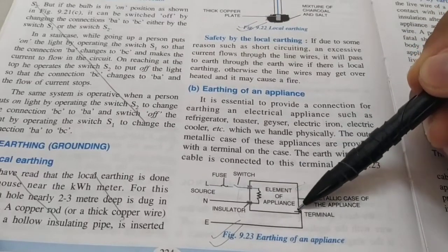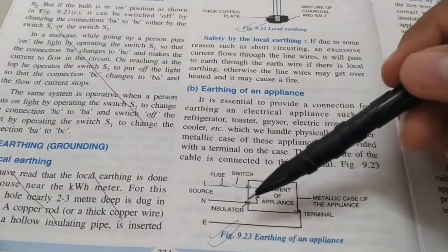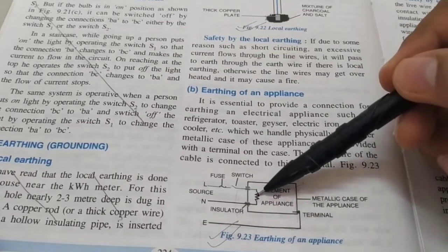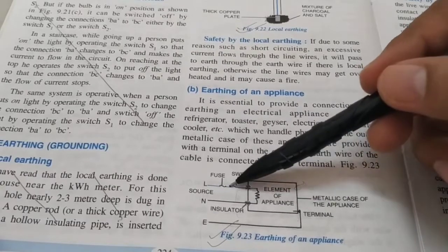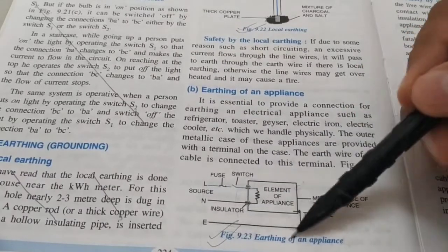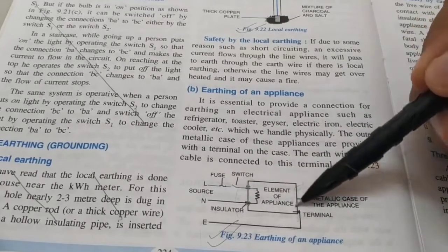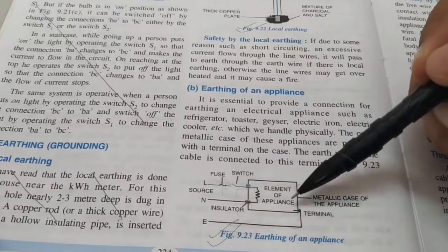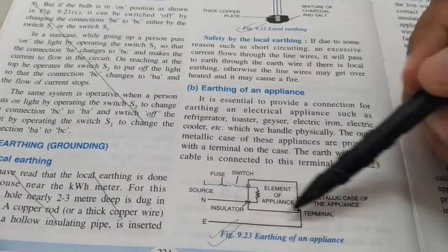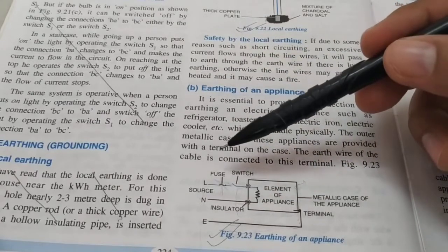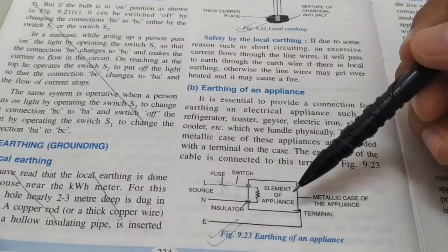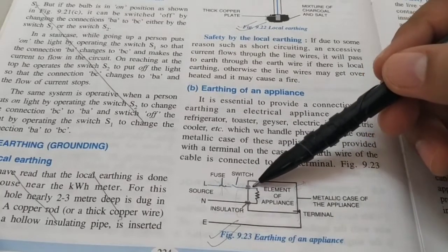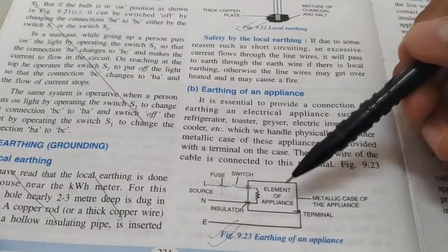The earthing is connected to the metal case, so that if at all current flows through it, the current will immediately flow through the earthing wire into the earth, and that will blow off the fuse. Because in this circuit there was some resistance inside, so the current was limited. The moment it flows through the metal wire and through the earthing wire, there is no resistance, and the amount of current flowing becomes very high, more than the usual limit, which will blow off the fuse. So the earthing and fuse work in tandem here, and if the fuse blows, we know that something is wrong and we are protected. Even the appliance is protected. Then we just have to repair this, maybe put in new wires and a new fuse, and we can start using the appliance again.